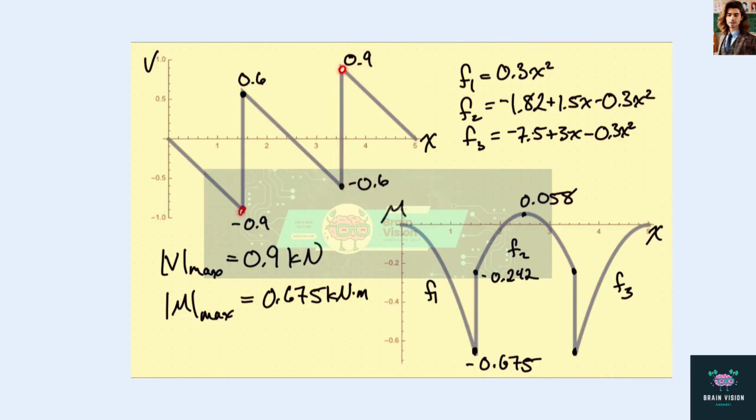So we have maximum shear forces acting where the wires attach to the beam, and then we have another negative slope from the weight of the beam, and we get back down to 0 here. Because we have lines here, we'll have parabolas here, and we'll also have some jumps because of the point moments. So in this region we have 0.3, I think I missed the minus sign there, minus 0.3